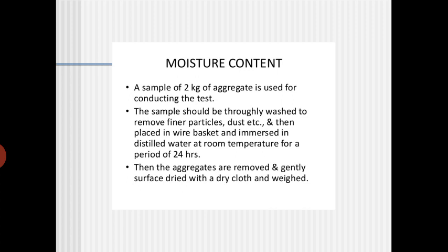I already said that distilled water does not contain any dissolved solids, which means the conductivity is very low. Normally, normal water consists of many dissolved solids and they are going to be absorbed by your aggregates. Once absorbed, when you want to get the correct moisture content of the aggregate, these dissolved solids will not allow the aggregate to dry completely.